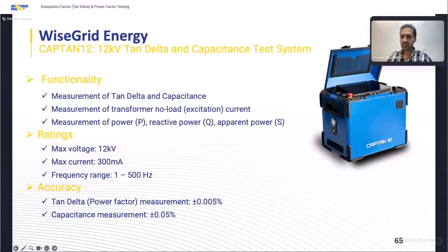No, there is no limit for C2 dissipation factor. I've seen an ABB document which says that up to 5% for C2 dissipation factor is allowed. So for about 2.3%, just check flange grounding. And you cannot compare it with the bushing nameplate, Mr. Luis, because when we put a bushing on a transformer, the value of C2 will change, also the dissipation factor value.